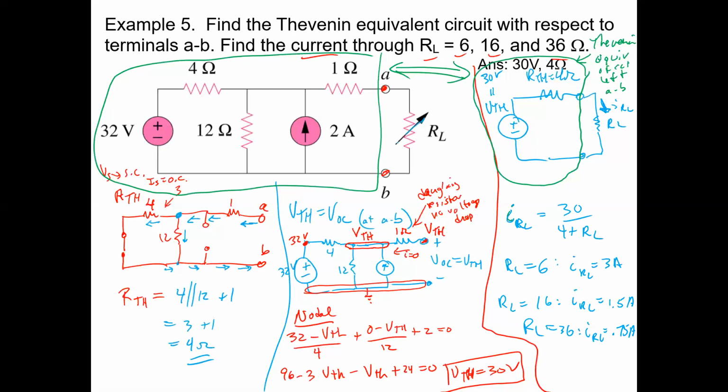Oh, this. Yeah, this just means it's a variable resistor. And we have one of those in our circuit kit. It's a blue plastic box that has a knob on it. Actually, there's a few different ones, but ours, I think, looks like this. As you rotate the knob, you get a different resistance between two of those pins. It actually has 3 wires on it, but it allows you to change the resistance, which is really good for tuning circuits to do things.